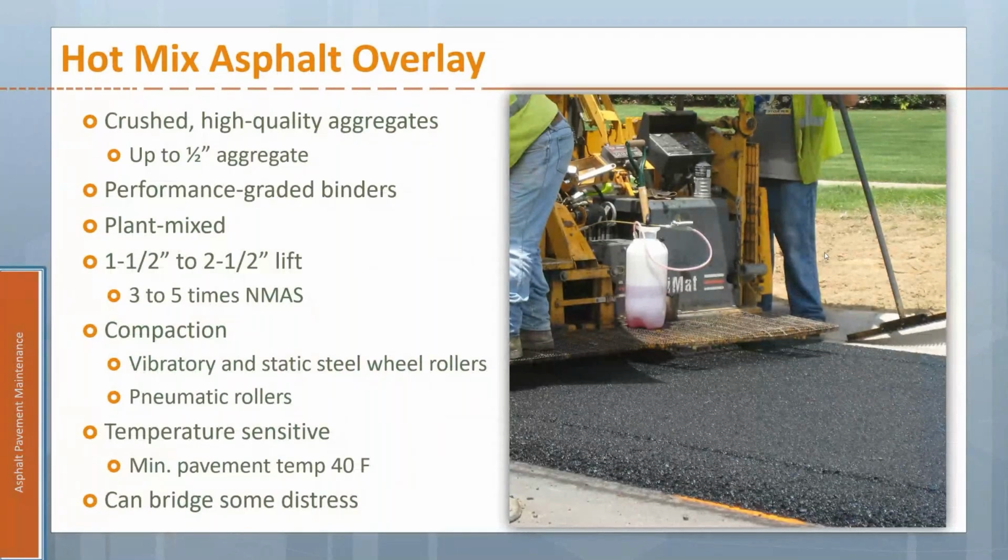And then here at the end, that traditional overlay, this is the kind of thing that you're probably all familiar with. So I'm going to kind of skip through that because that's not really the point of this, but just as comparison, you'll have these slides to go back and look at. But 2-inch typical surface layer and normal asphalt type things. So we're back to what's normally done. But all these other treatments that I've told you about can be a surrogate for having to spend the money for that true traditional overlay, because that is not cheap.